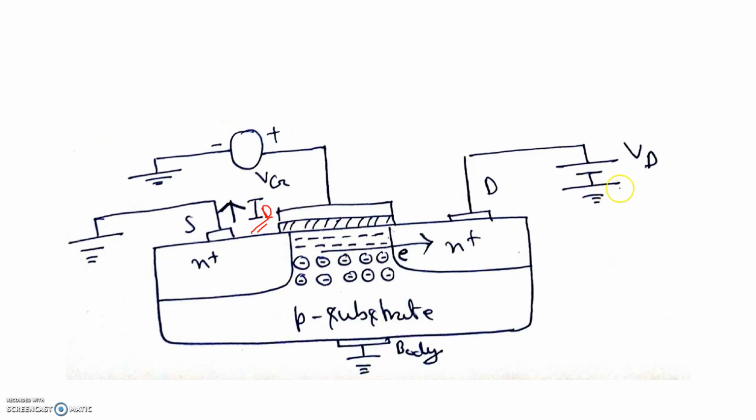Now you carefully observe, you keep on increasing this potential. How can the device burn out or break down, go to the breakdown region? Just try to think in a very logical manner. No need to remember anything, just carefully observe this figure and tell me, is there somewhere a PN junction in reverse bias? Because breakdown occurs in reverse bias, right? Zener or avalanche breakdown we have already studied in detail in the semiconductor device and circuit course. So our first motto will be, is there somewhere such a region present where the PN junction will be in reverse bias? Okay, yes, that is present.